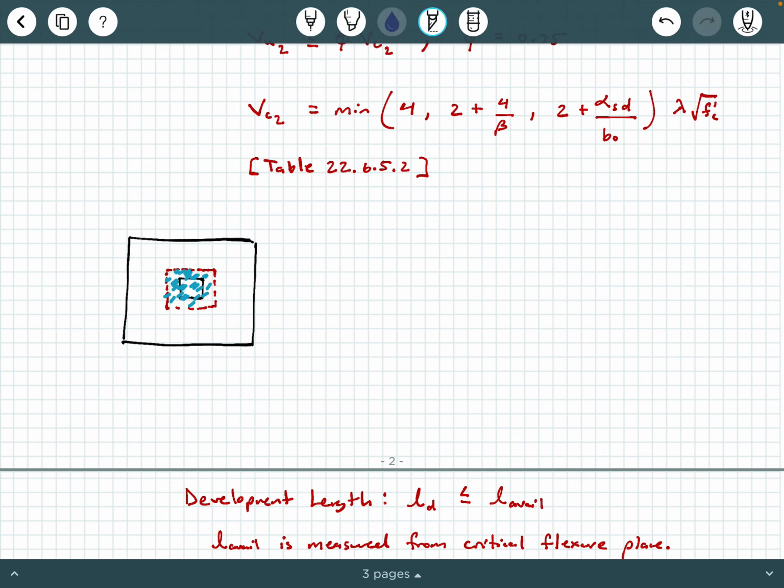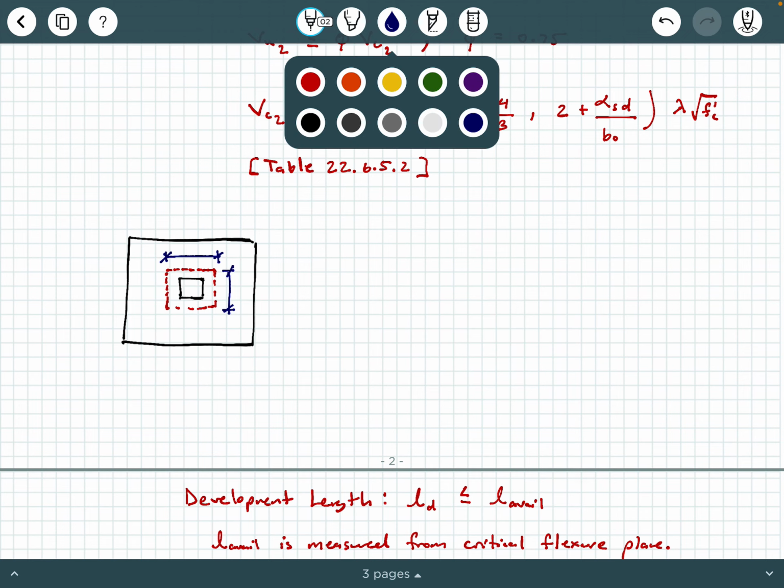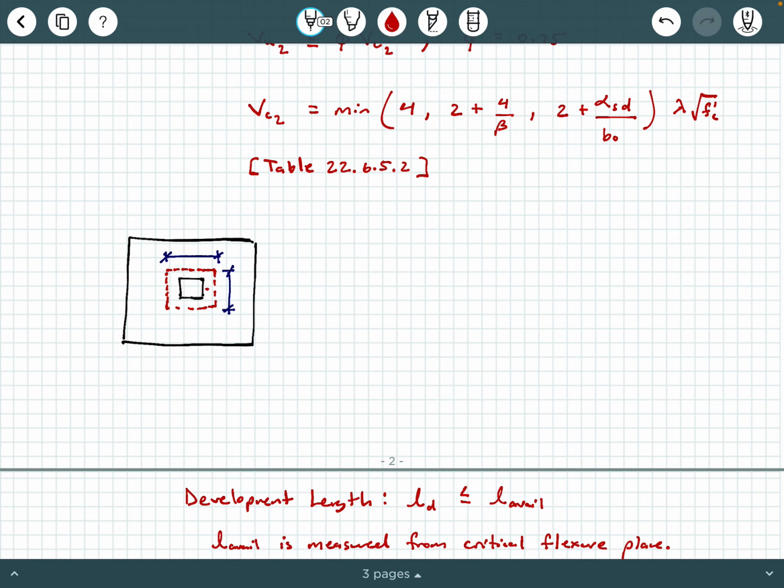Well, it's going to want to punch through this larger area that is surrounding the column, okay? We call this perimeter the punching shear perimeter, okay? Now, what are these two dimensions? All right, well, the punching shear perimeter is going to be defined based on moving a distance d over 2 out in the two principal directions from the column, okay?